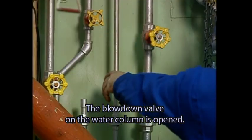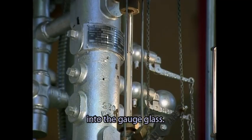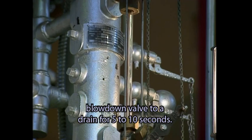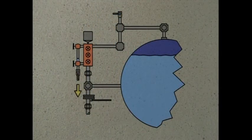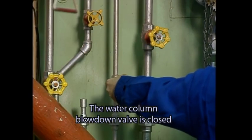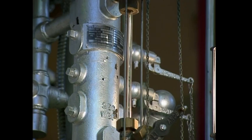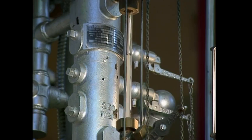The blowdown valve on the water column is opened. This prevents any debris from the water column from being carried into the gauge glass. Water and steam should discharge through the water column blowdown valve to a drain for 5 to 10 seconds. The water column blowdown valve is closed and water should return to the gauge glass. The water should return quickly and flow without interruption.